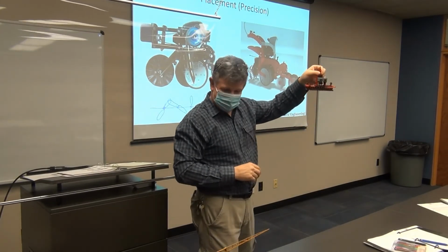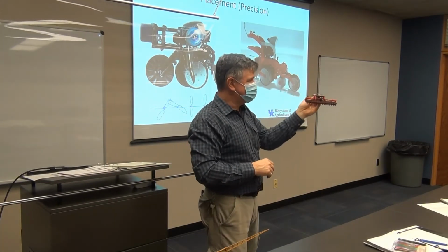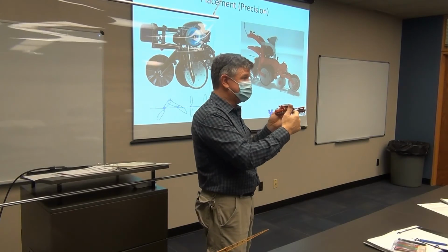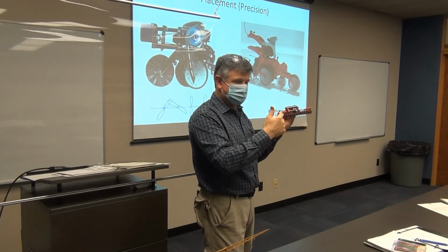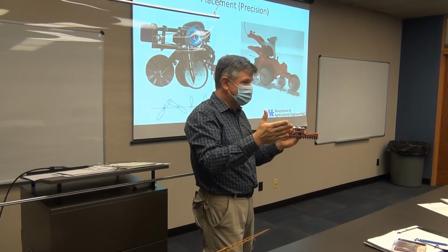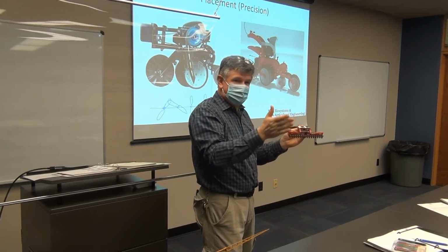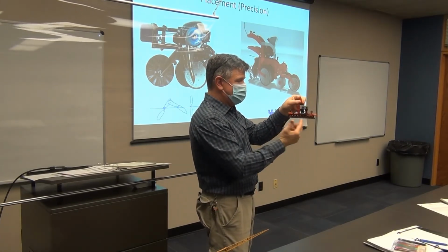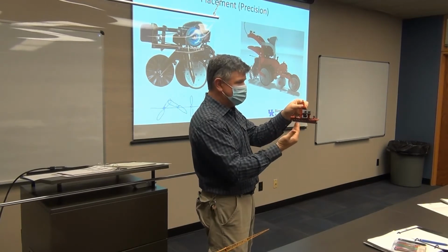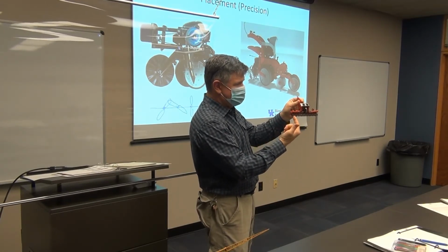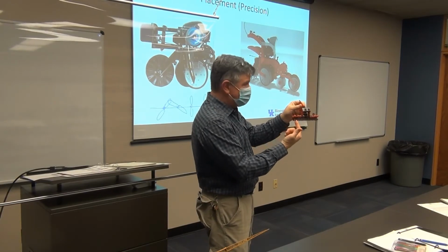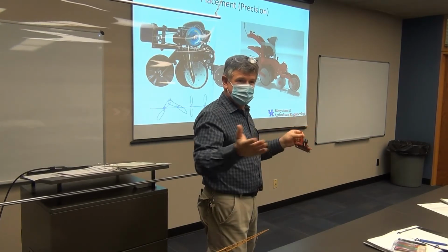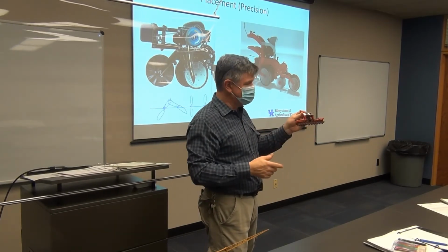So there you go, that's a typical planting machine. This is typical corn, what we call a precision planter. Again, most of the time it's corn, sometimes we'll also do soybeans. Often we don't plant soybeans in as wide a row as corn, so soybeans are typically every other row. Sometimes they'll build planters with twice as many units and then they're staggered. So there's one in between, with two toolbars or something like that, and a second set of planting units so that one lines up right in between each of the other ones. And so then I get rows every 15 inches instead of every 30 inches. And then I use the same machine for soybeans.